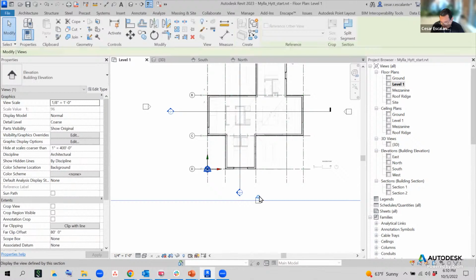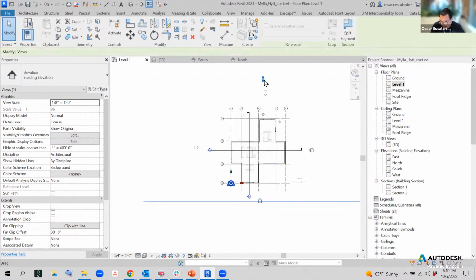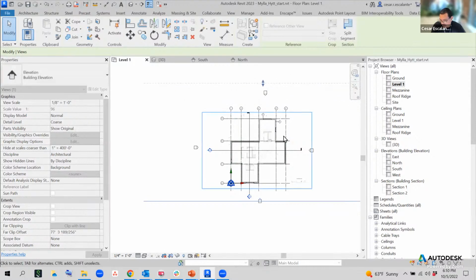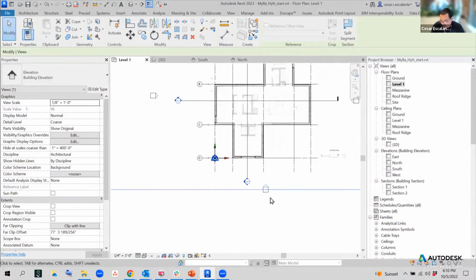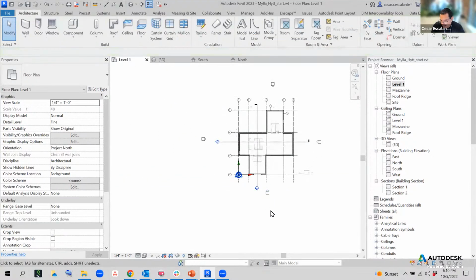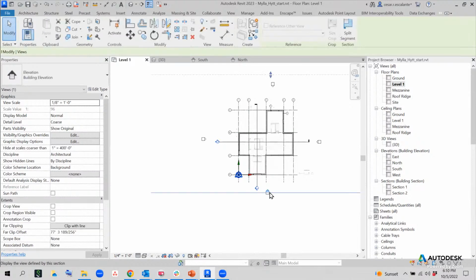Make sure when you select the view that the view depth is deep enough so that it captures the entire building. The view depth is controlled visually by this double arrow, and you can select it when you select the arrow in the key. Okay, got it. Thank you.